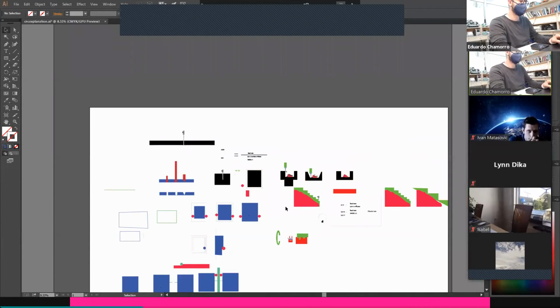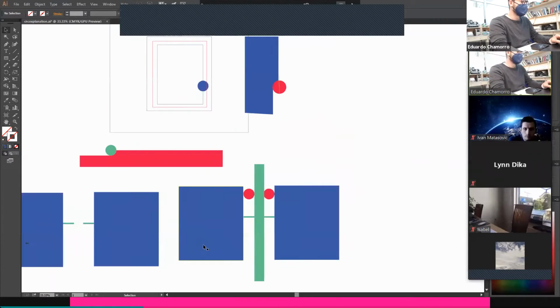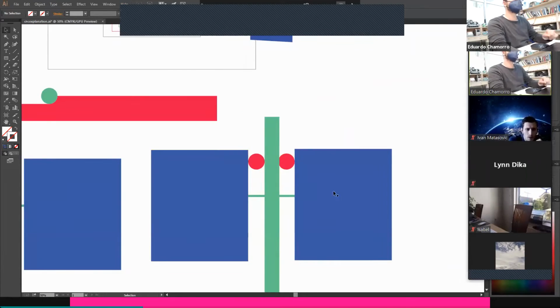This is about 3D milling, and how much space you leave on your parts. When we make an outside cut, this is the tab we want to leave to hold the parts. This tab might change depending on the material you are using. You want them bigger or smaller, depending on the material.